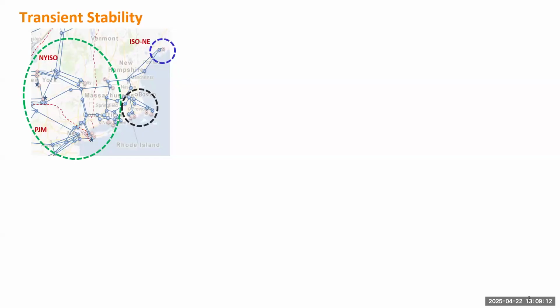Because we learned small signal stability, a large system may have many oscillation modes. There may be a local mode, and interarea modes. For the interarea modes, you will see a group of generators oscillating against another group, maybe the rest of the system. So it's totally fine if you see coherent groups of generators. Some generators tend to become closer to each other, but some will have a different phase. As long as over time the generators stay together closely around the same frequency, we still consider the condition stable in terms of transient stability.